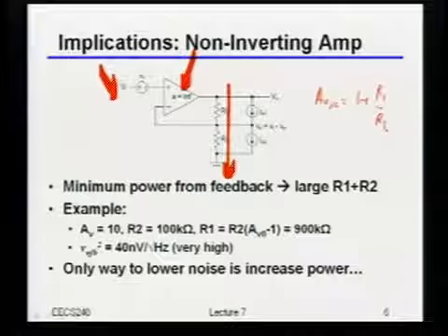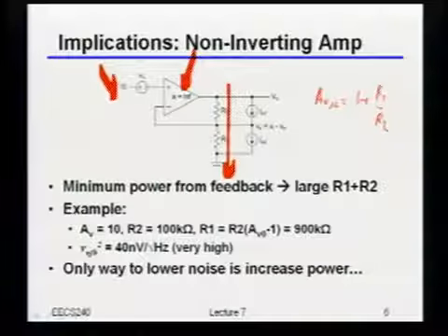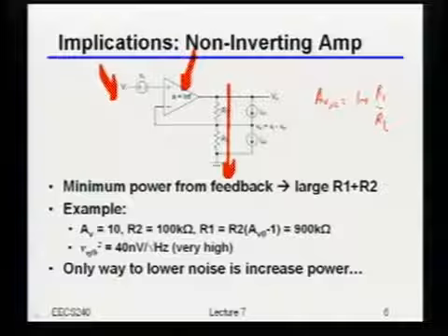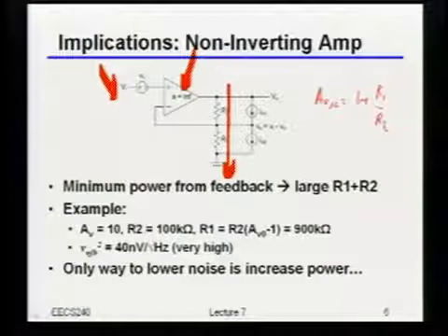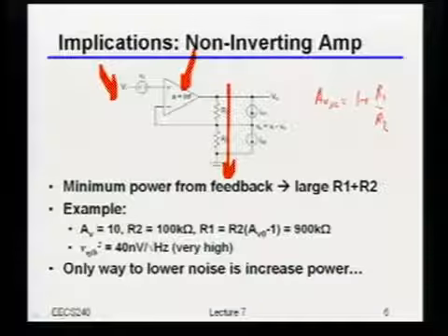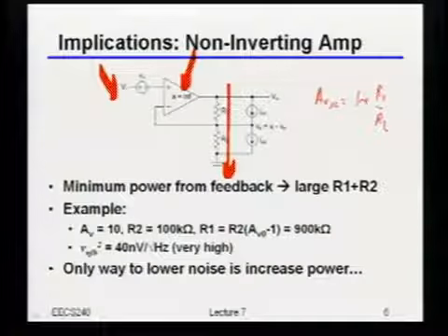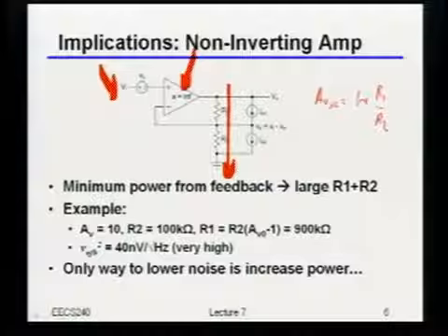Or you just tried like 5 different chips until it worked. Anybody ever looked at one of those spec sheets? No, okay. Well, so maybe I should really give you a homework to go and look up one of those spec sheets. But just to give you an idea, again, a good op amp is probably sub nanovolt per root hertz input referred voltage noise.